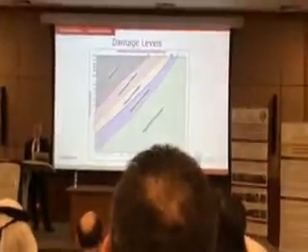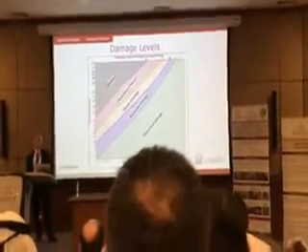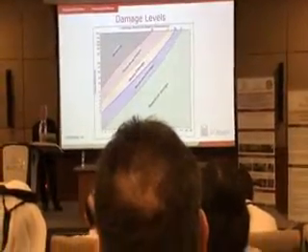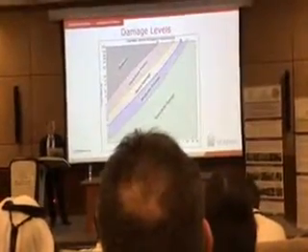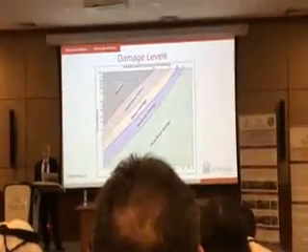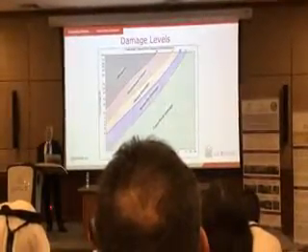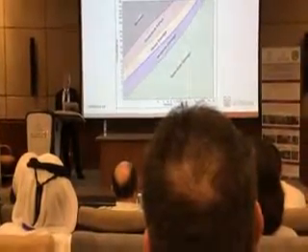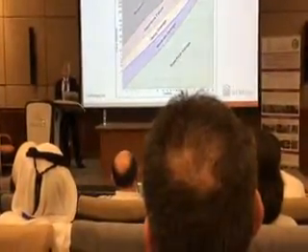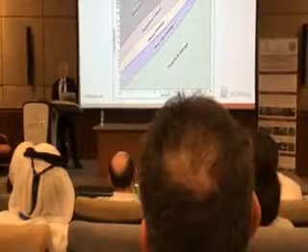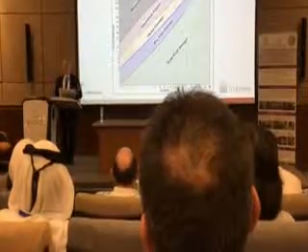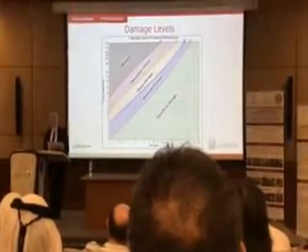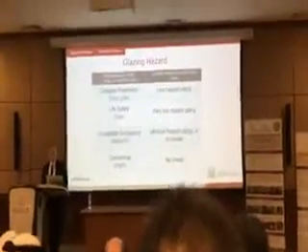And once again, if you have, let's say, 150 kilograms of bomb at, let's say, 3 meters, it's hazardous failure, right? If it goes up to, say, 10 meters, 30 feet, it's on the border of heavy damage and moderate. So these charts are also available, or you can develop them if you use them very frequently.